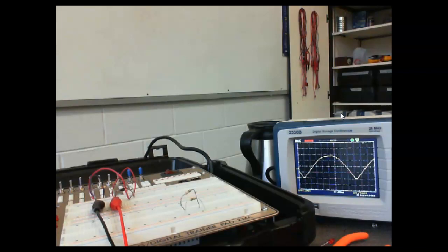So now I know this is 60 hertz for 1 cycle. So 8.33 milliseconds. If we took the reciprocal of that, it would give me 120 for a cycle. So this is 120 hertz, cycles per second, because now we're turning in both sides. So this is what it looks like on an oscilloscope.